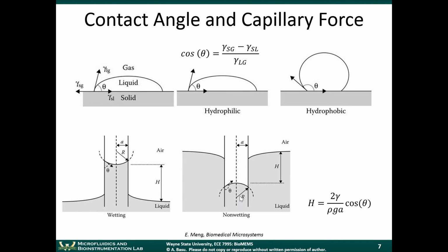So there's two things that work here. It's the exact inverse of this problem. You have the hydrostatic pressure that would try to drive this liquid up into the capillary. Hydrostatic pressure is just the fact that you've dipped a capillary down into the depths of a liquid. Just like if you took a straw and you put it to the bottom of the ocean, there's so much pressure at the ocean it would just come right out.